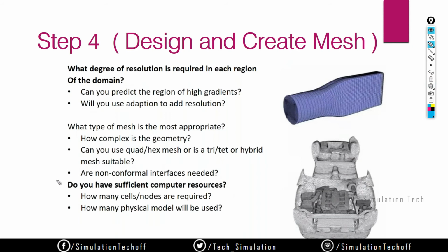And the next thing is, do you have sufficient computer resources? Most people make a mistake on this point, whether they have sufficient computer resources or not. By using a simple laptop, you can't solve complicated problems, especially a 3D problem. Most people ask, sir, I want to model this 3D component in a CFD analysis. You can't. For example, take the interior of a car design. When I try to mesh the whole body, obviously you have lakhs and lakhs of nodes and elements, so it will take some days to solve the problem.